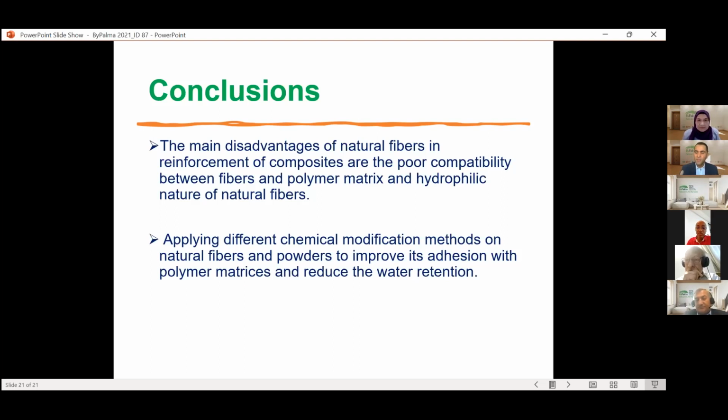There's a very specific technique that we use for making the thermal insulation bats that are commonly used nowadays with linen, flax or even hemp fibers, which follows a carding method or a dry laying method. The fibers are blended with specialty springy fibers, bicomponent fibers, that provide the high loft for the thermal insulation bat, and also mixed with a low melting polyester fiber.